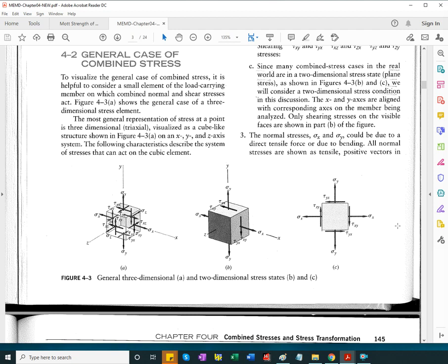So I started saying that in a pressurized pipe, on the outer surface, you're going to experience axial load, the longitudinal stress. You will experience the hoop stress, and then if the pipe is also twisted, then there are shear stresses that occur.